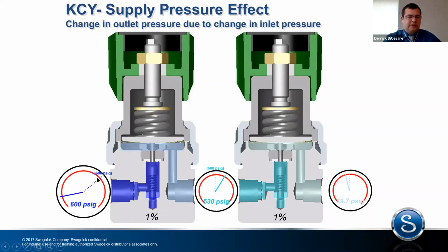In the same scenario, we've lost 3,000 PSI in the inlet. The cylinder's nearly depleted. The effect that that has downstream on our system is 0.3 PSI. And it's a decrease, so we don't have to worry about seeing a surge in pressure downstream that can affect mass flow controllers, gauges, transmitters, GCs, anything else.